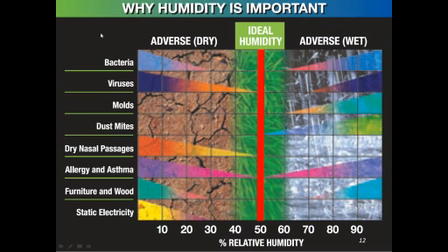If I were to maintain even 50% in my own home, it's going to go down to 11 below zero tomorrow, Fahrenheit. If I were to maintain even 50% humidity, 40% or 60%, any place in the ideal range, when I would get up the next day, all of my windows would have a tremendous amount of condensation on them.